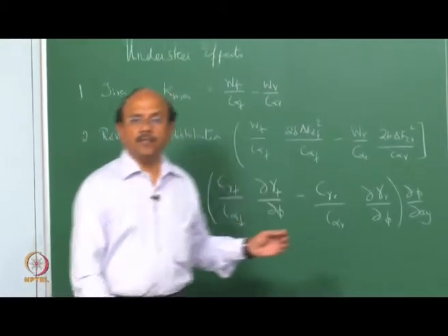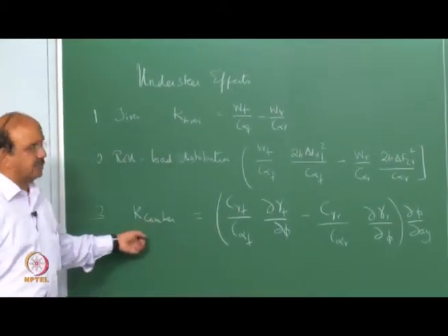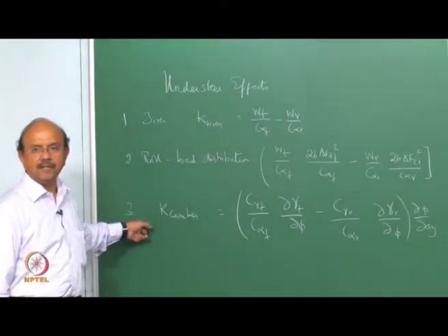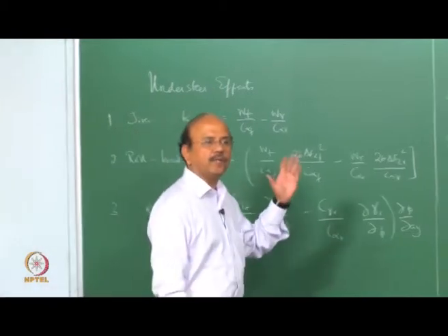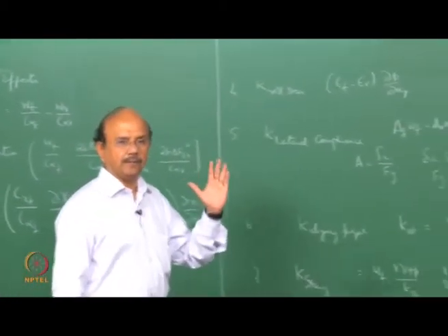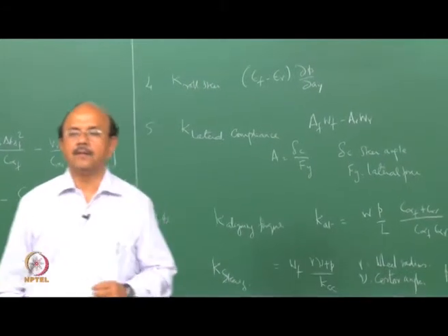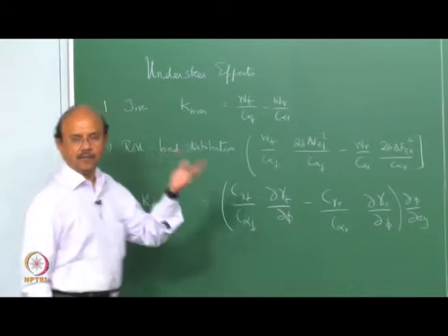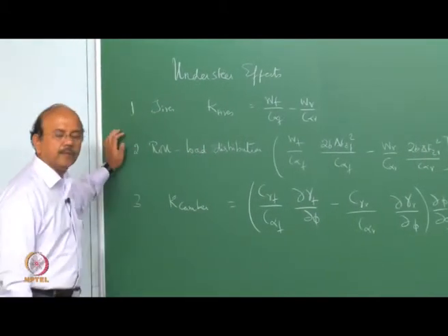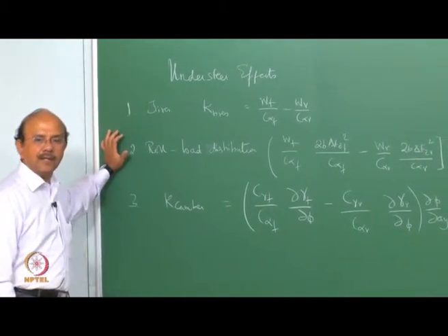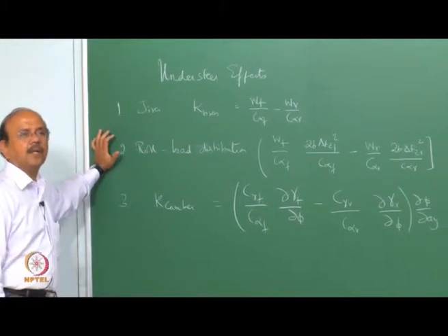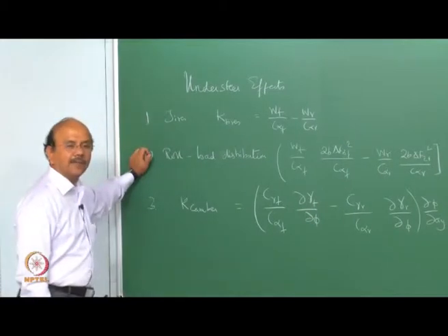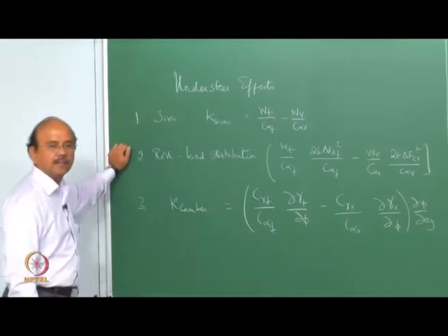The next we saw is with respect to the camber thrust. Remember that we defined camber thrust as the lateral force produced because of the presence of camber of the tire, or in other words, the wheel. We saw that the slope of that curve, the camber force versus camber angle, becomes important, and that's what we call C gamma f.